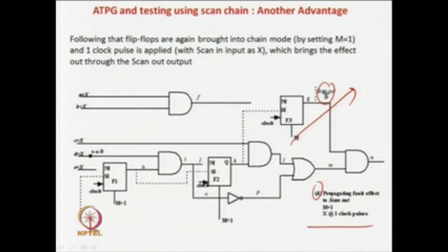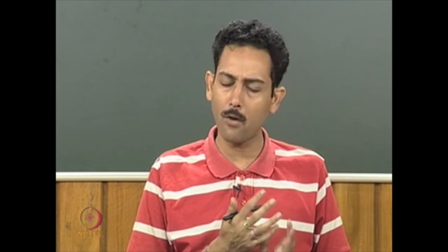In the previous approach, you take a scan chain, set the scan chain, apply the pattern and get the fault effect to the primary output. Your job is done. But there you have to consider all the flops, set them for all the faults, patterns for all these, as well as do ATPG on the whole circuit. That was a big problem. So, now how have I solved it?